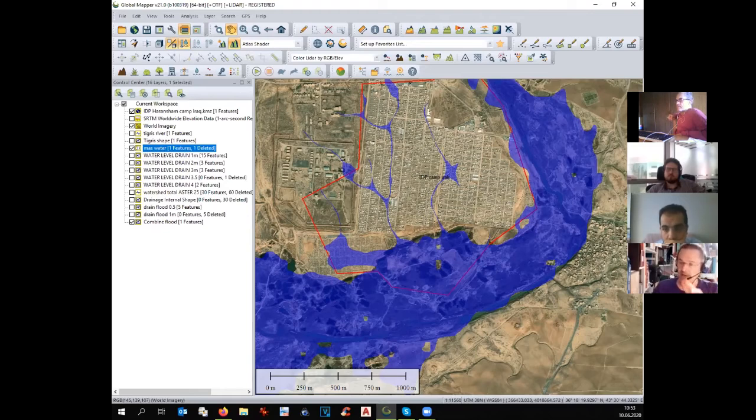Andrea, at the beginning of his presentation, was introducing the idea to have some geo-referenced points, which means you go to the field, you speak with the hosting community, and you ask them to indicate on the ground the position where the water reached, for example, last winter. So you take the point. As Andrea was doing, raising the water table until you get to the point, and you have an idea more or less of the behavior of the water also in other parts of the settlements.